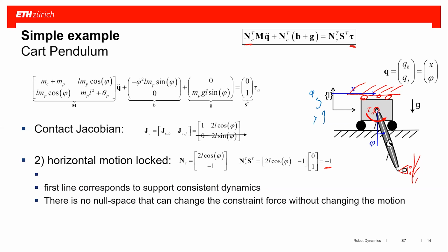If I have a constraint on velocity, if I have a constraint on position, I have to propagate this to a constraint on acceleration level. In an ideal case, when initial conditions are all valid, you can just look at the acceleration. If you had to numerically stabilize these things, you would have to have feedback gains also on velocities and on positions. But we are not looking at this in here.